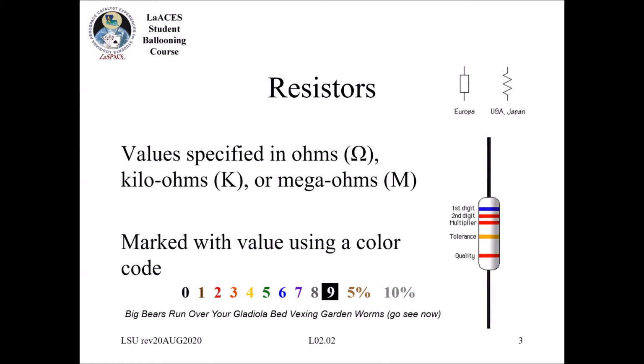Also, be aware that there are standard values that you can order with resistors. Whenever you're calculating a value in a circuit and you look at it from a vendor, it may not be the exact one, and you might have to start putting some things in series or parallel to get the exact value you need. And this little saying underneath here is just a way that you can try to remember all of these colors off the top of your head.